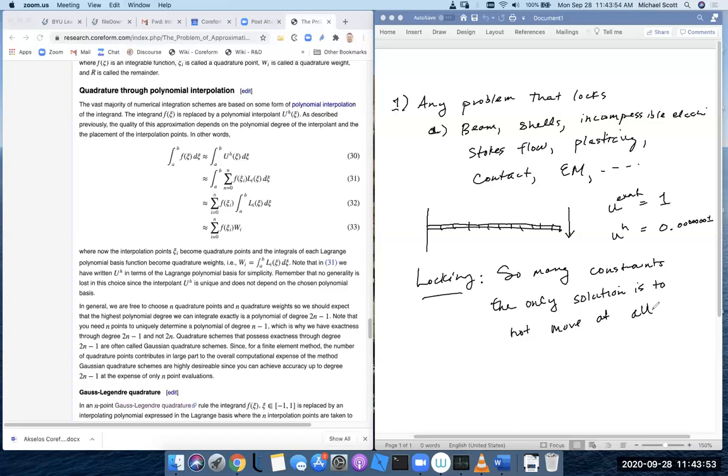Incompressible elasticity is a little easier, right? You have an actual constraint, a second equation that's imposing that the divergence of the stress is 0, right? That's a constraint. And if you apply that constraint in too many locations, your solution will lock up. In fact, that constraint actually has an optimal number of constraints with respect to the primal basis that you're using for displacement.